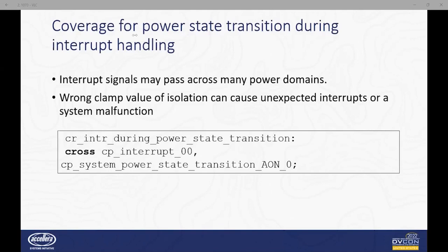As the coverage model checks the interrupt generation and handling over power mode transitions, any malfunction of interrupts or power transition errors can be detected. In addition, it will help to identify any missing system-level scenarios regarding interrupt handling and power transition use cases.